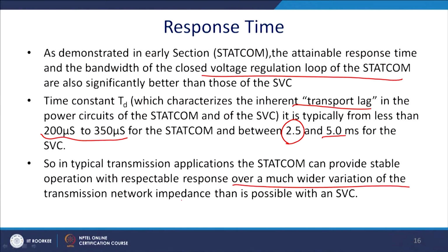So, in a typical transmission application, the STATCOM can provide a stable operation with respectable response over a much wider variation of the transmission network impedance than is possible with the SVC. So, of course, we can say that in transient stability also the STATCOM supersedes the SVC.